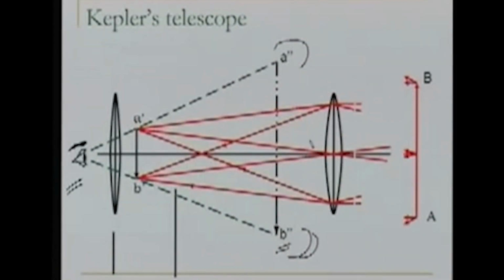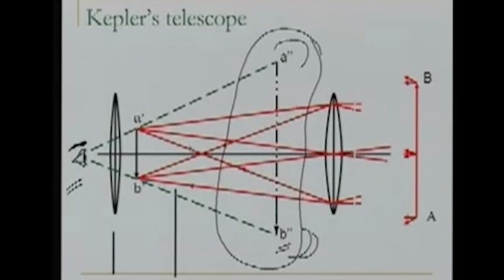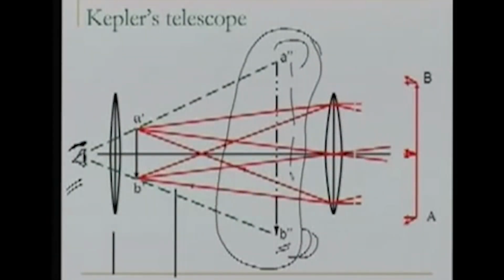There may be some extra lens, additional lens, which will invert this image, because at this moment you are seeing the ranging rod inverted. Though it doesn't matter for an experienced surveyor, it is alright. He knows how the image is generated and he knows how to take the observations. But in order to expedite the survey, in order to avoid this kind of confusion, the modern instruments are fitted with some extra optics in between, extra lenses, and they will further turn it and the image will look erected.